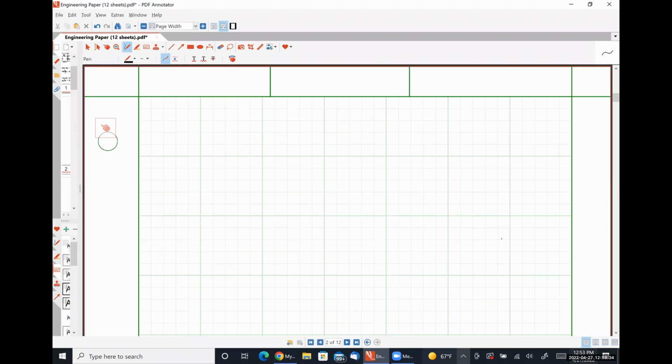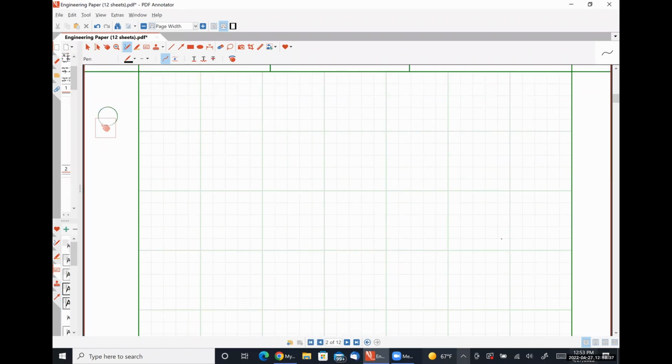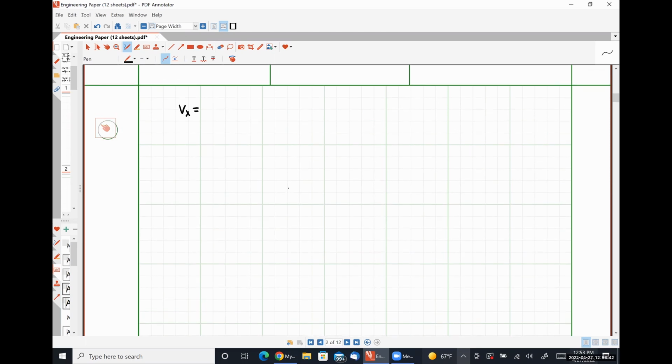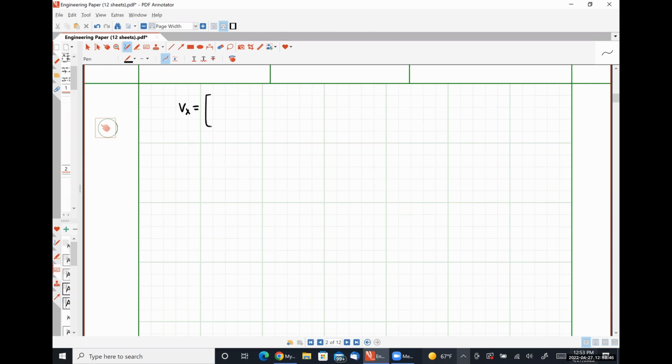So from here, we would have Vx is equal to (GM2 plus S CGD1 plus CY) divided by (negative GM1 plus S CGD1). Do I need to go back and look at something? Are we good? No, sir. Okay.